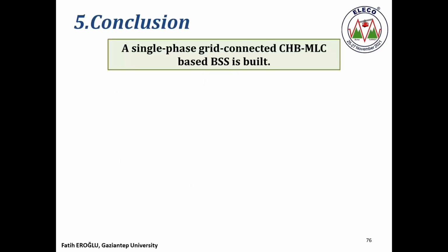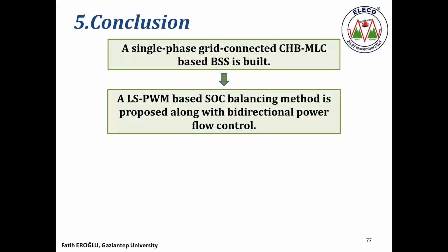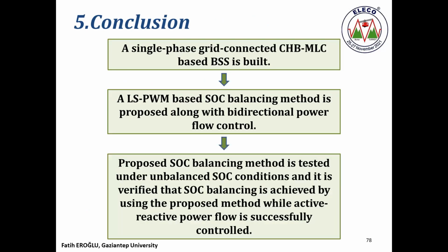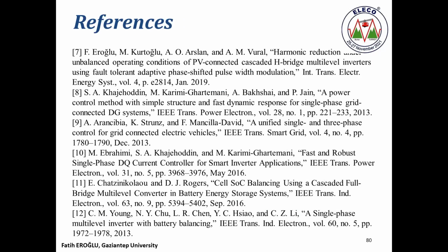So to conclude, we designed a single-phase electronic multi-level converter-based battery storage system, and a level-shifted PWM-based SOC balancing method is proposed, along with a bidirectional power flow controller. It's verified that the proposed SOC balancing method is tested under unbalanced conditions, balancing is achieved, and active and reactive power flow control is also successfully obtained. So these are my references, and that's it.